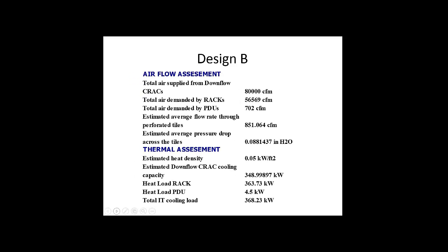So this is a summary of the input side. A little bit more here about it. We've got 4 cracks, 80,000. They're 20,000 apiece. Total demand, 56. So again, this one was built for an N+1 case, is what I suspect. And in an N+1 case, you can see that's running pretty much at capacity. N+1 would be, if one of these guys was down, you'd be running 60,000 at 56. So now, when they're all up is when you have the issue, of course. When they're all working, you've got an RTI that is way too low.